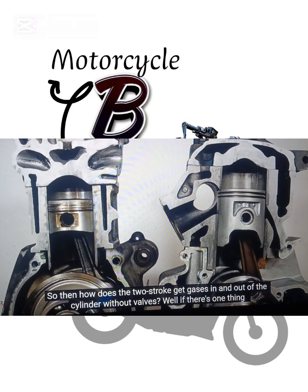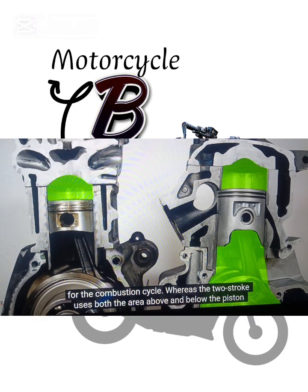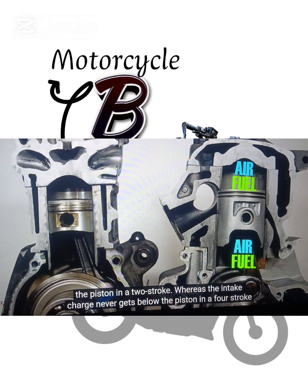Well, if there's one thing you should take away from this video, it's this. The four-stroke only uses the area above the piston for the combustion cycle, whereas the two-stroke uses both the area above and below the piston. In other words, the intake charge, or air and fuel mixture, sees both the area above and below the piston in a two-stroke, whereas the intake charge never gets below the piston in a four-stroke.